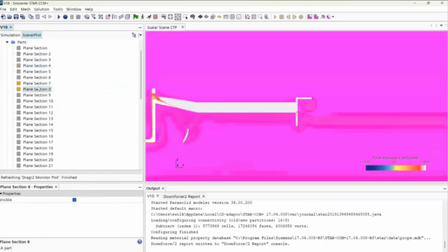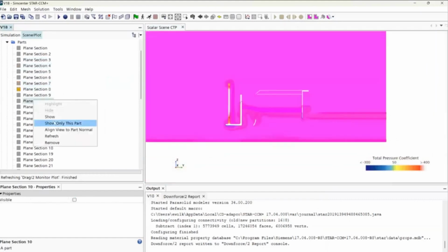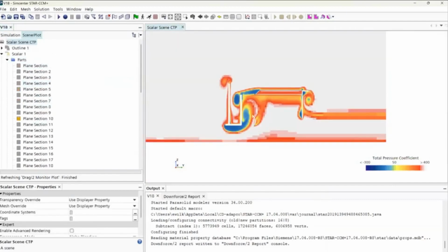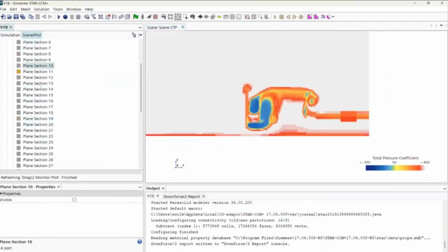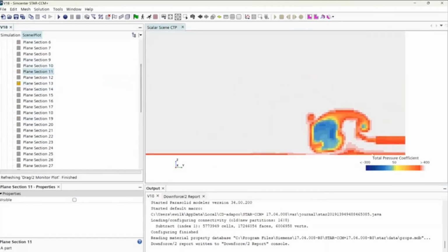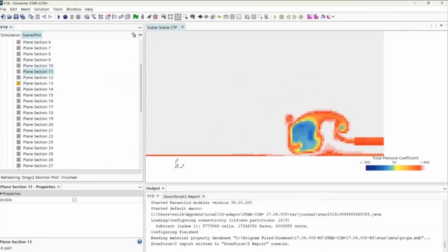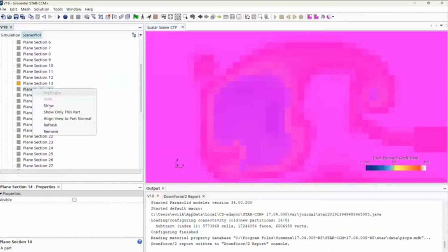and if you go later on, you have this vortex creation here, and you can go through these planes and visualize how the air is flowing. You got some loss here, vortex, and you can go through all these with total pressure coefficient, which means ambient will be the highest, and the more you affect the air, the lower it will be. So you'll have low pressure in the middle of a vortex, obviously, as air is going very fast there. Well, take it with a grain of salt.